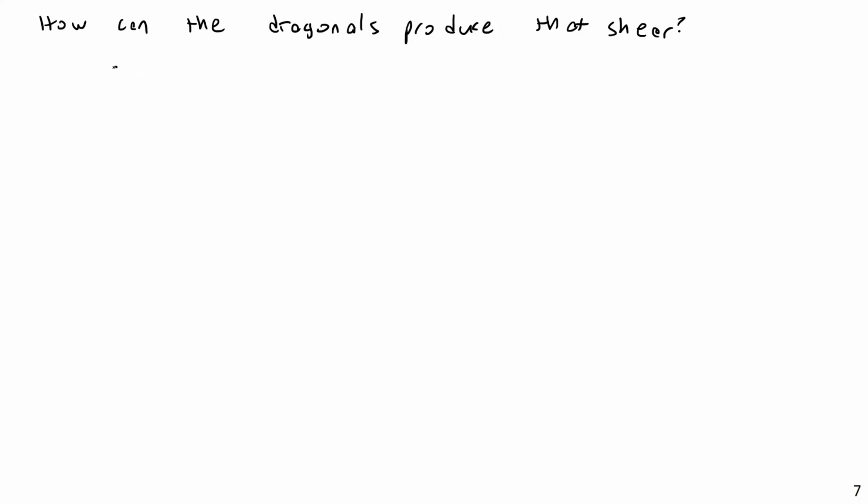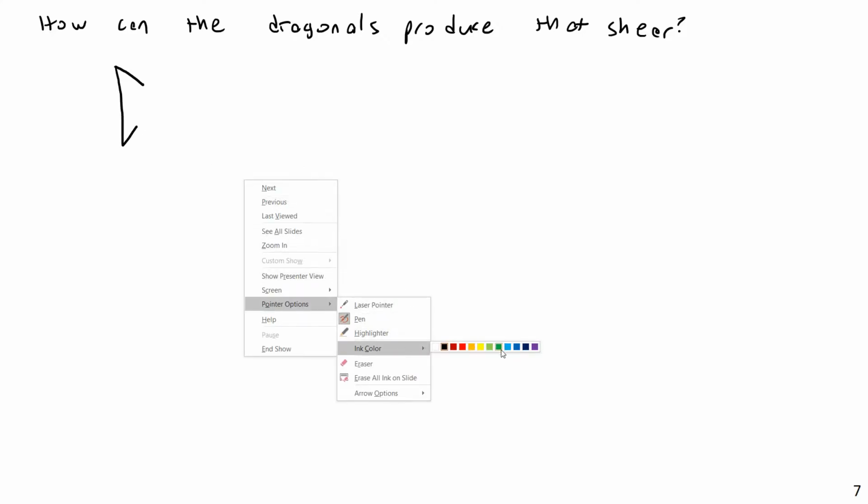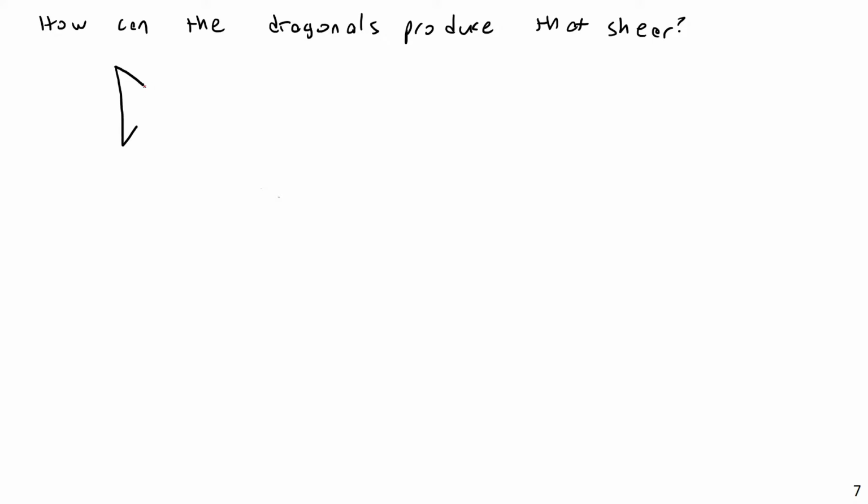Well, first of all, let's draw this out. So F2 and F3. We have F2, we have F3, as I drew it before, and we had 22.5 kips, and we said these two must equal a downward force of 22.5 kips. Now, as I have this drawn, they're not both going to be contributing to shear.